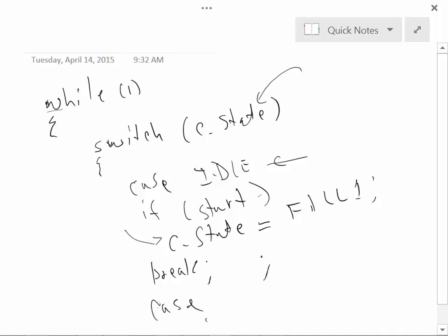So it's that there. If anything else happens in the idle mode, we don't care. If the time expires, which it should, because our timer shouldn't be running. If the door opens, nothing should happen. If somebody walks up and presses the reset button, and then of course it's already in idle, it's going to stay in idle. So we don't worry about anything else. We just simply look at the start button there. So our next state we would then go through would be our fill 1.